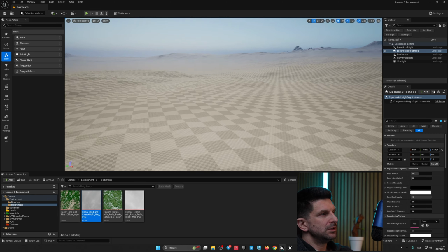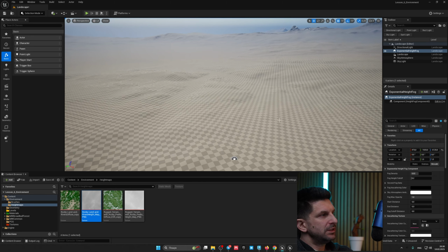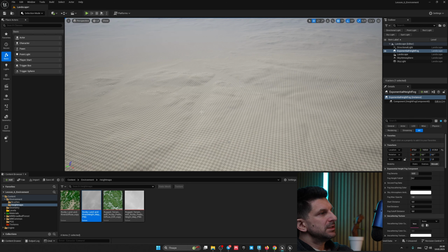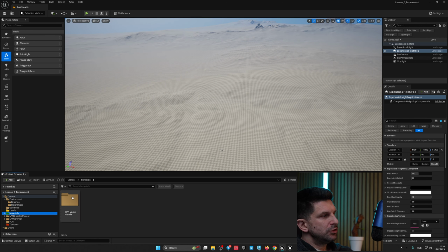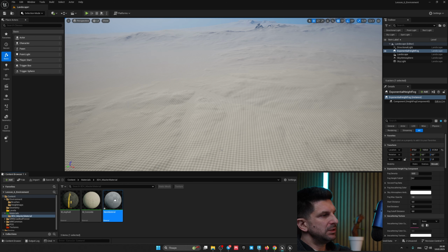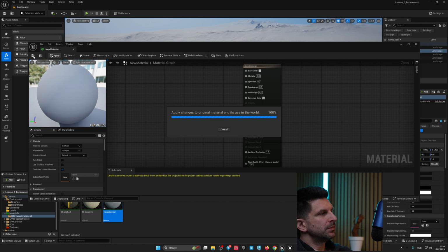As we see, we don't see the edges because it's still 2 kilometers. But let me add something else, so those squares don't confuse us. I'll assign it to the landscape. Material. Material is assigned to the landscape a little differently. I'll create a simple gray material. I'll remove the specular.